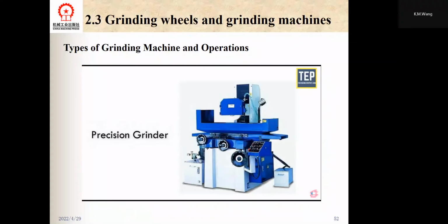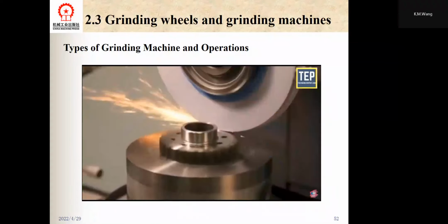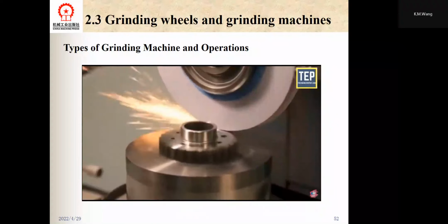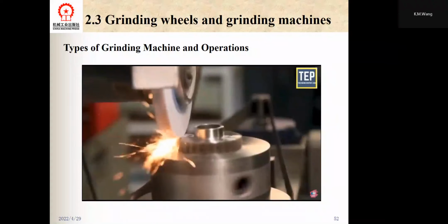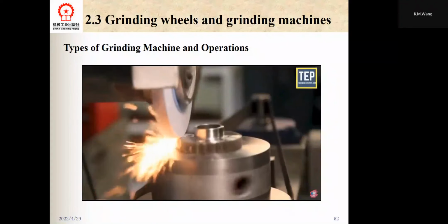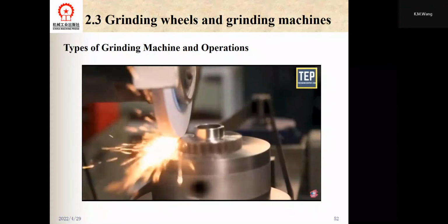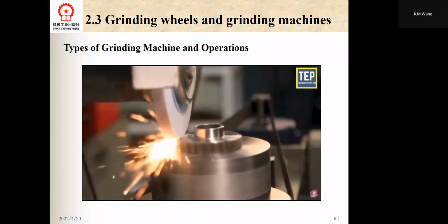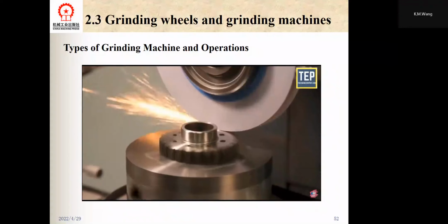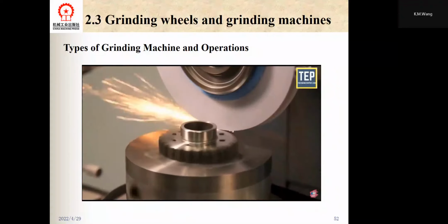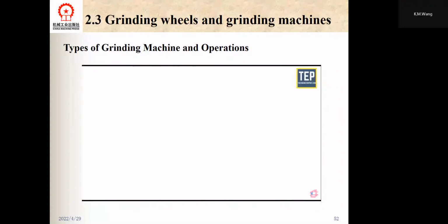Precision grinder. In this type of grinder, a movable spindle is fitted to the grinding wheel. This spindle is fitted on a table along with the motor. With this spindle, the grinding wheel can be turned in forward, backward, left, or right direction, in running condition. Jobs of excellent finish and accuracy are ground with it. There are various types of precision grinders available. They are: